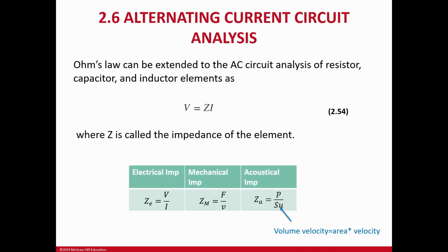So we need to learn the analogy in another domain. For example, in the mechanical domain, voltage is analogous to force, and current is analogous to velocity. So this is called mechanical impedance. Same thing in another domain. For example, I am working in the acoustic domain, and the effort side is the pressure, and the velocity side is the velocity times the surface.